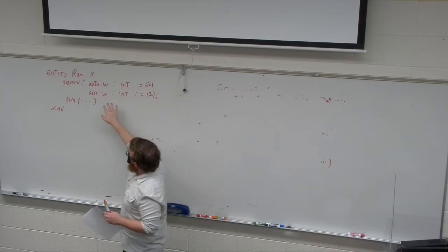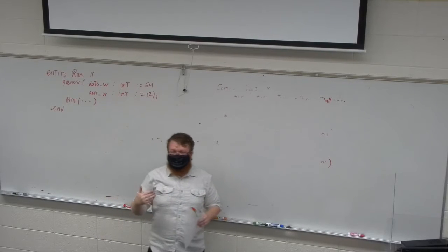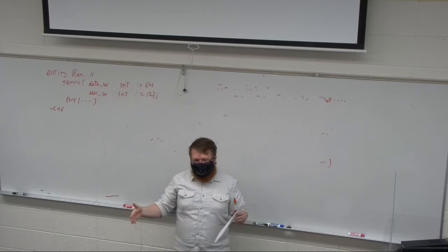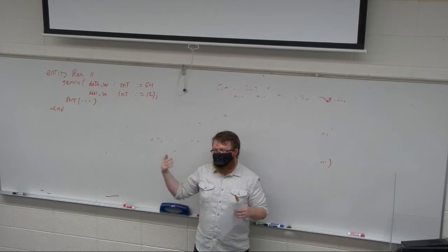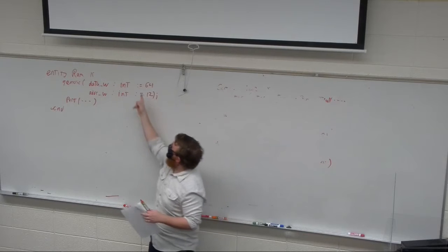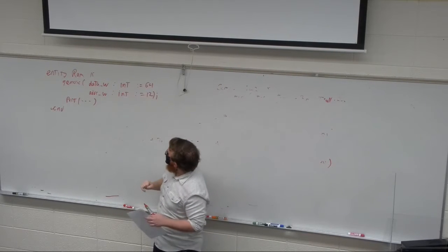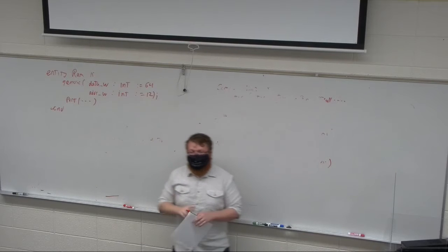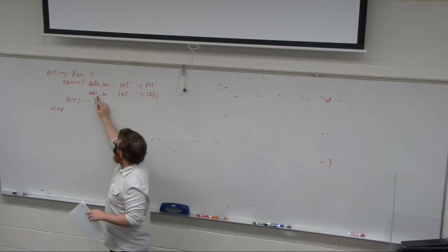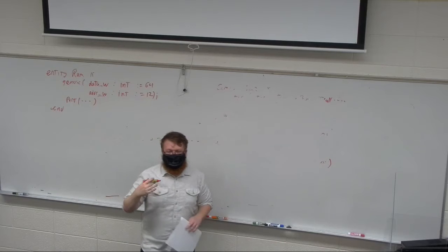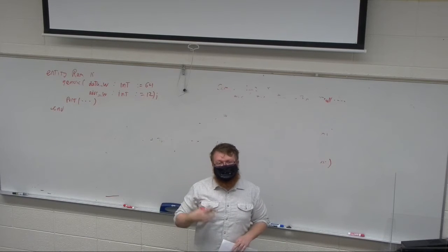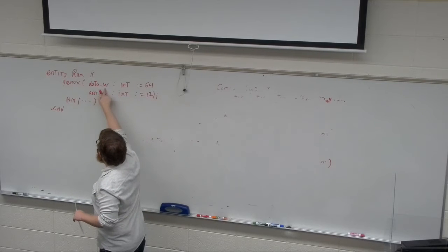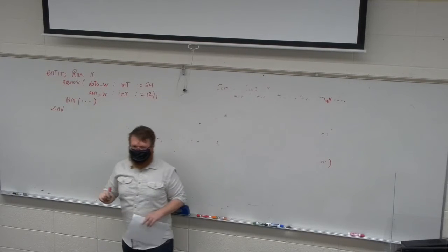We want to have varying data widths, meaning how many bits are available at one time, and varying depth, which is how big it really is. In this case, it would be 64 by 2 to the 12. The address width is how many bits of addresses we have, and you can then calculate everything else you need with just these two. So this is the width, and this is the depth.